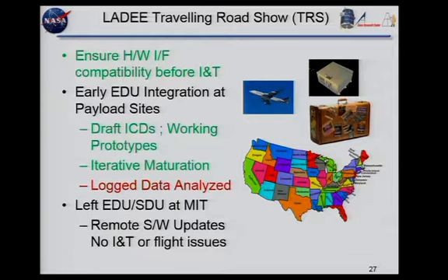So we actually took an EDU out there that had an RS-422 card off the shelf in a CPCI chassis, and we left it there. CompactPCI is a modification of the PCI standard. It's basically what you have inside your PC, the interface for putting cards in. It's a compact version of that. So it's pretty standard, and the cards are pretty inexpensive as well.